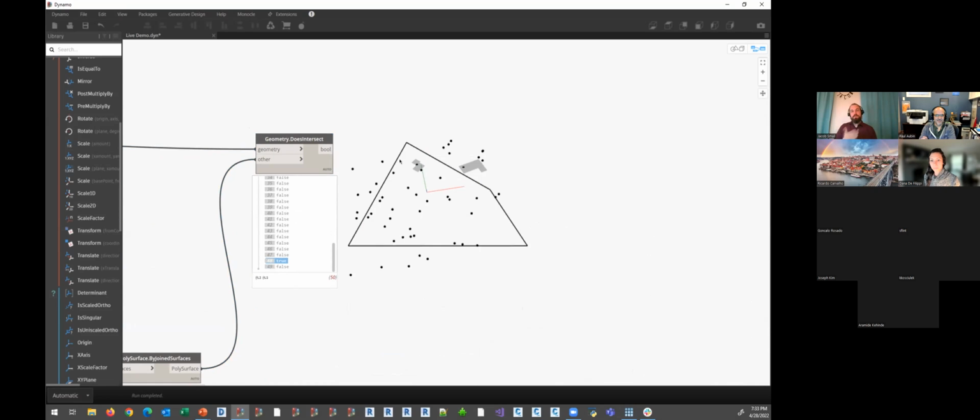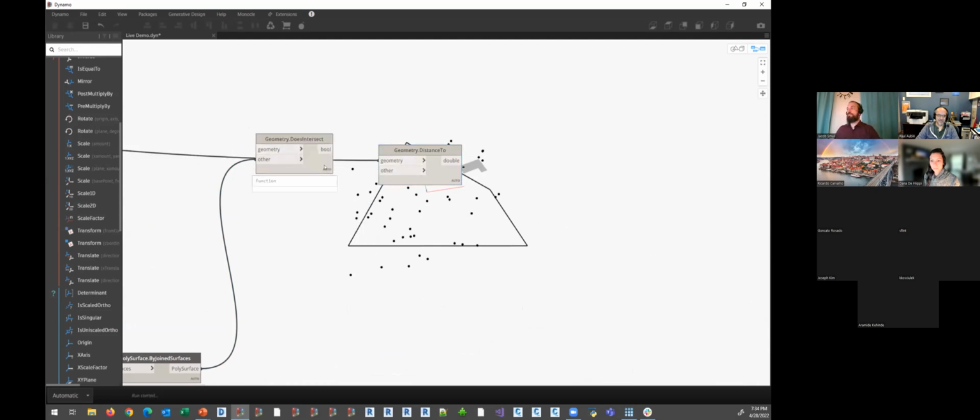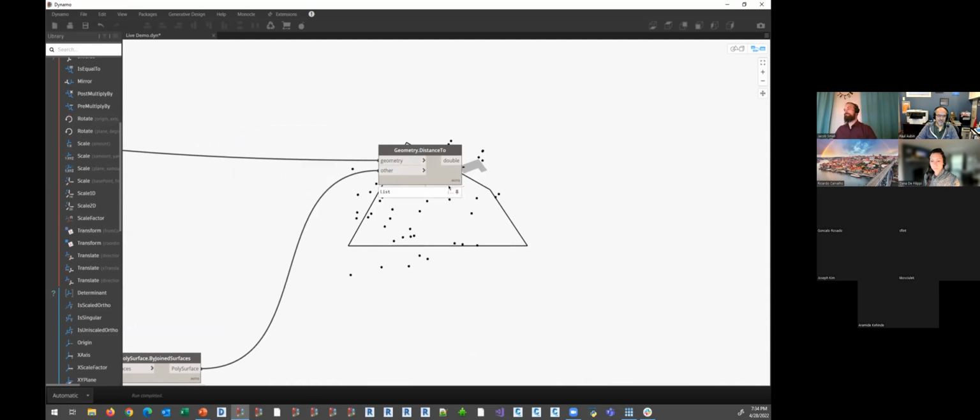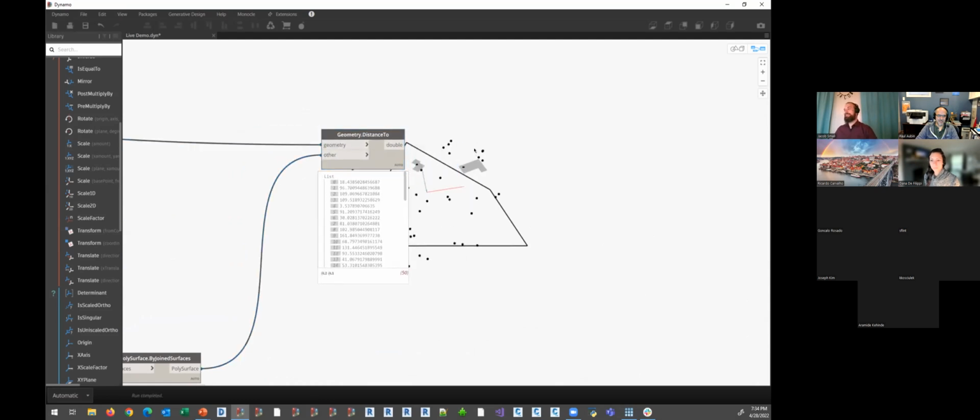We could also get a little bit more particular. How close can I really put a building to a tree? If I miss that thing by a half inch, is that tree going to last? No. Let's use instead a Geometry.Distance2. Helps if you spell right. And once again, we can take all of our trees and test them against the combined sum of all of the buildings. And now I can ask, is that value less than 10?